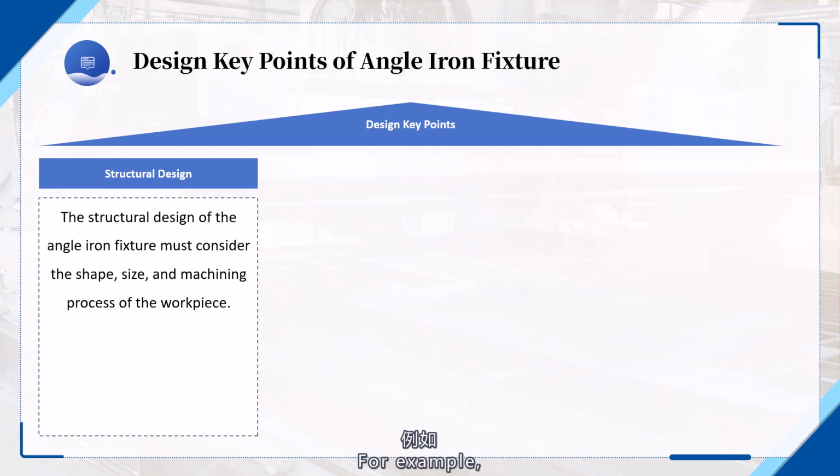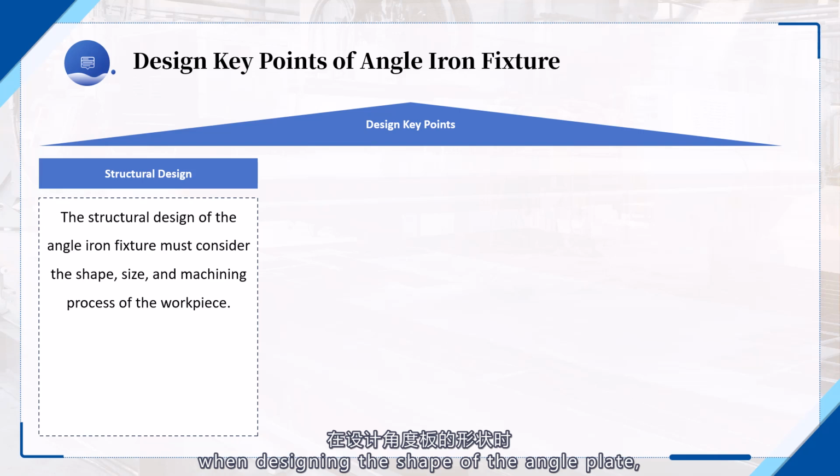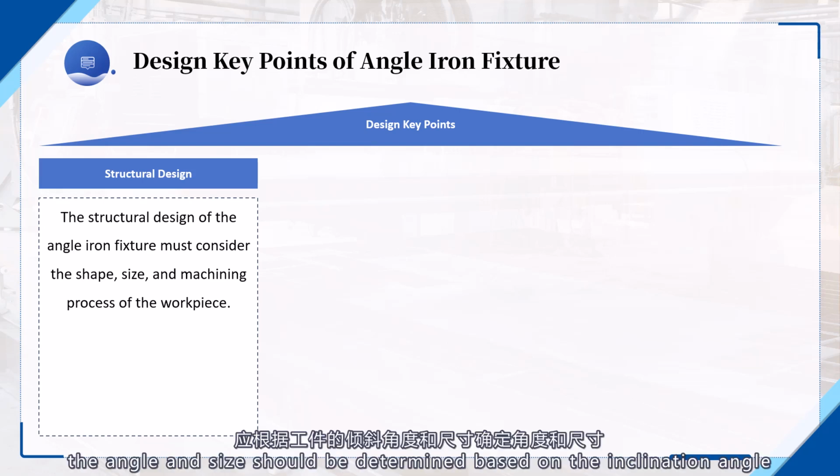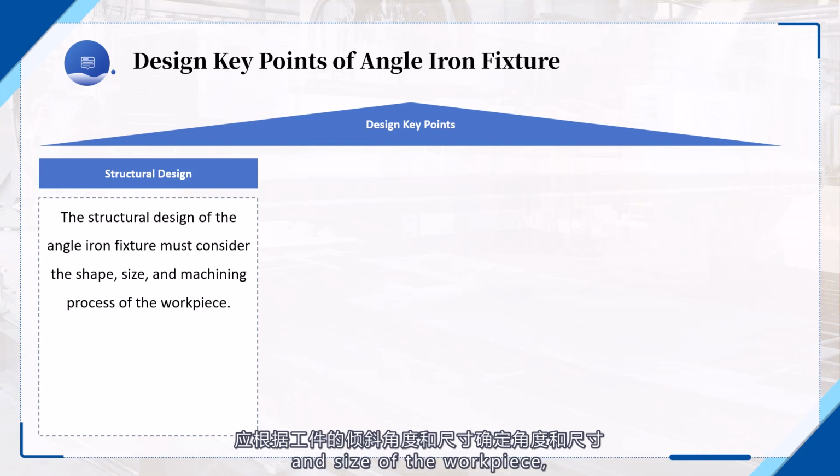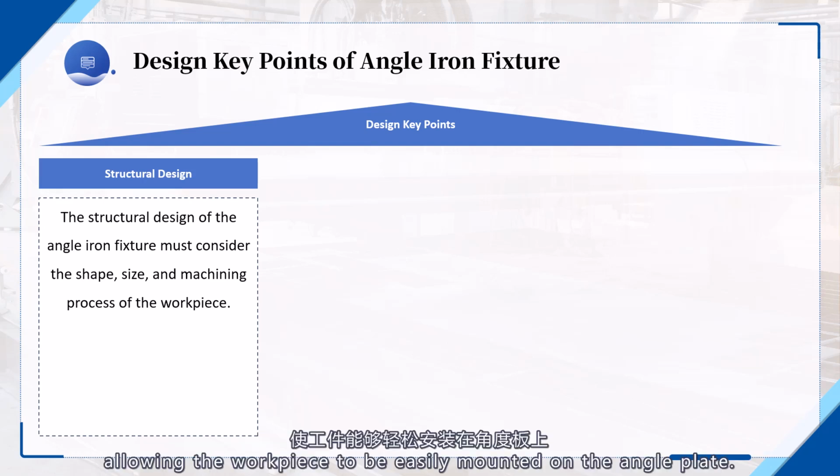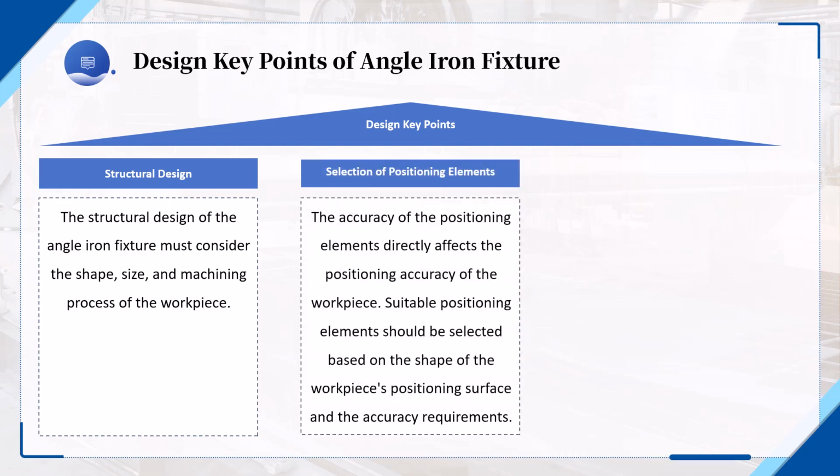For example, when designing the shape of the angle plate, the angle and the size should be determined based on the inclination angle and size of the workpiece, allowing the workpiece to be easily mounted on the angle plate.